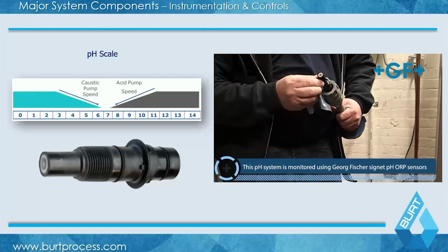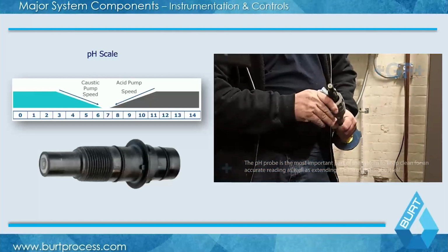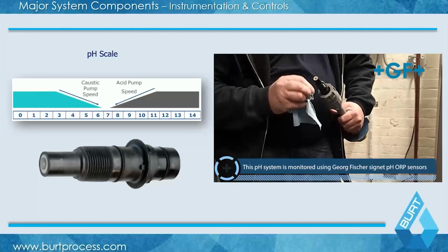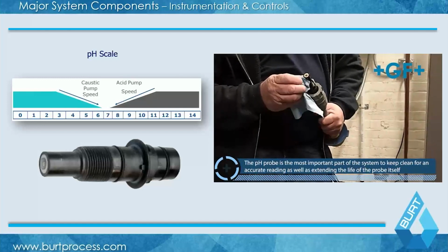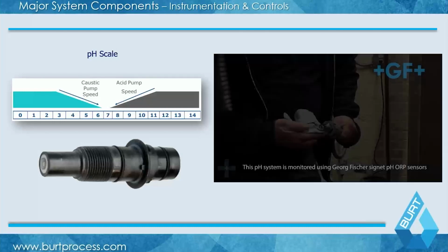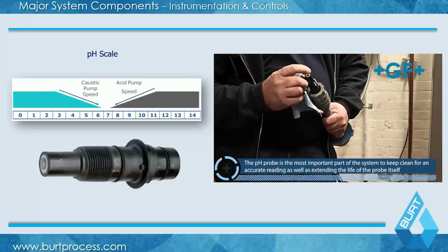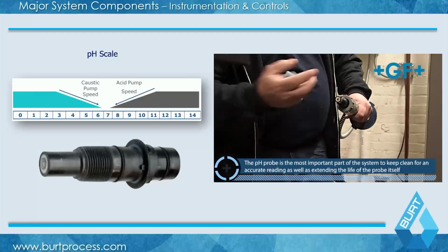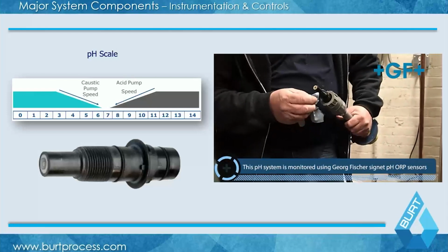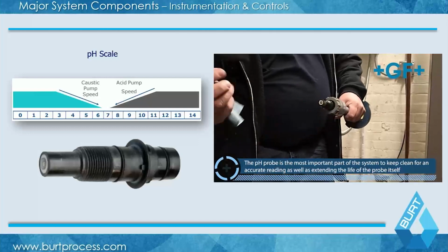One of the things I didn't really talk about before, when I was talking about residency time and the different treatment tanks, and we're going to talk a little more about how you do a flow profile and calculate that, as it relates to pumped versus gravity flow systems. But as part of an actual pH system, we talk about CSTR and residency time. Residency time is effectively the tank volume divided by the flow rate. And the tank volume is set by your maximum instantaneous flow rate through the system, which can be hard to determine. But you need to base it on what you believe the instantaneous flow rate could be, not the averages or a low end, because it's during those high flow peaks that you have the potential for an out of spec condition.